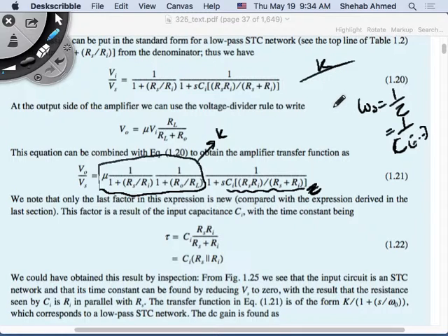Is the frequency the same everywhere in the circuit? Look at it. Don't answer me without looking at it. It's not frequency dependent. That's the right answer, right? So if it's not frequency dependent, maybe I can just put frequency equal to 0 and then eliminate my capacitor. It's an open circuit, and find the voltage gain like I did before.